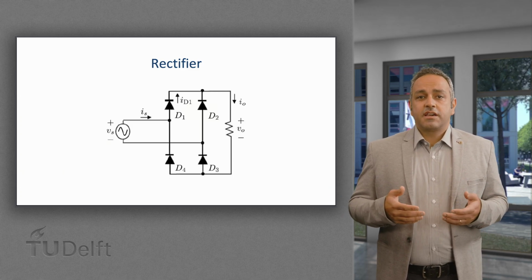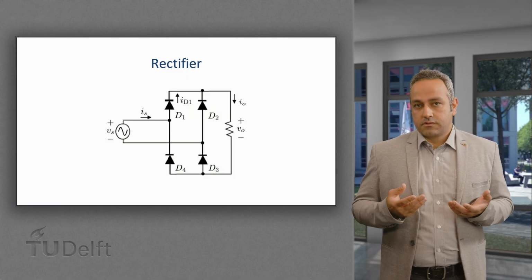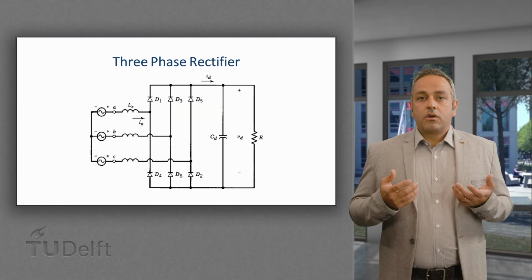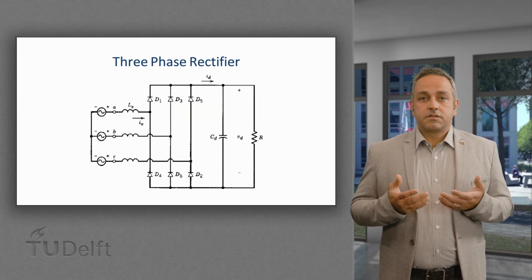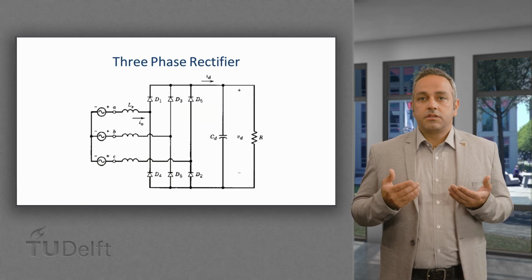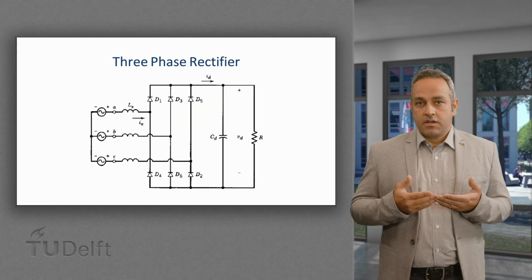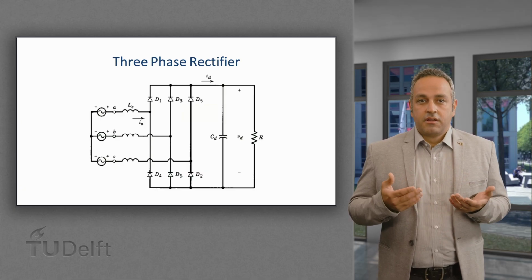Today, we analyzed a very simple topology consisting of only four diodes. However, more complex technologies are used to process the input signal into a more constant output DC voltage or into a different DC average value. The topology used today is only a simple example.